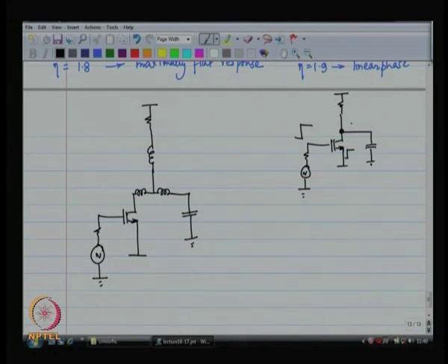So, initially the voltage was at power supply, now you would want the voltage to go down. This is the basic idea. This should be the ideal step response. Now, because there is a capacitor over there, this is not really going to happen, and even when the current goes through a step response, because the load is an RC, the capacitor is going to charge up slowly. Okay. So, this is what you are going to achieve out of this first cut.